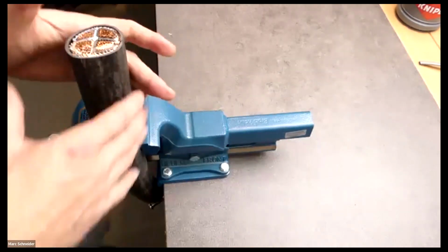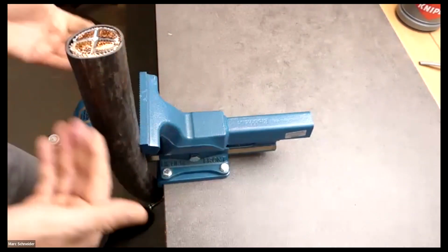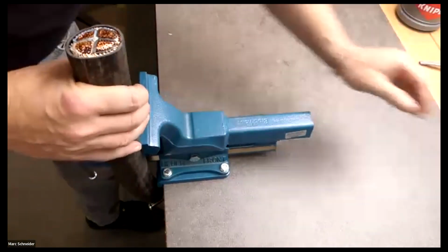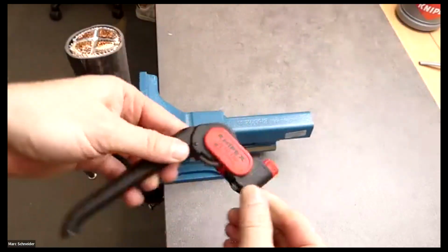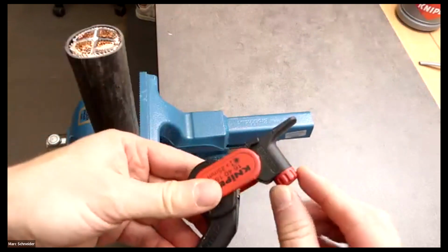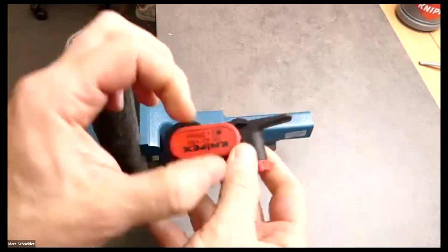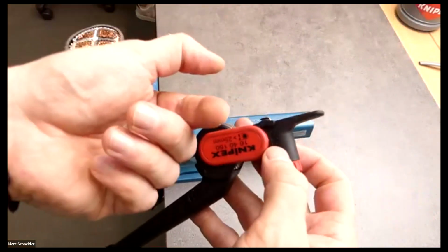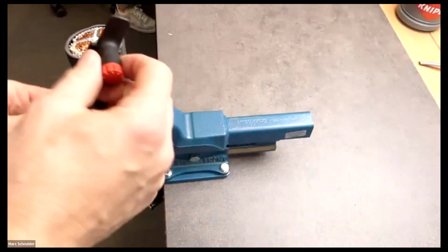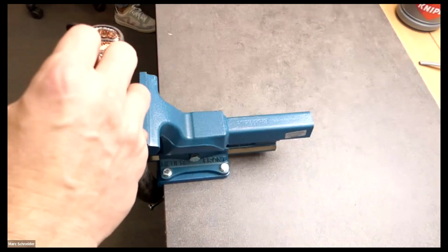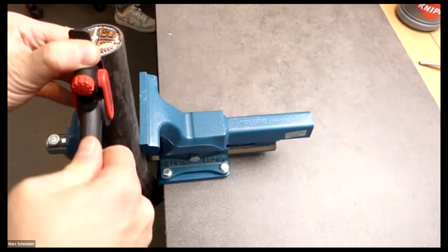This here is a cable. It's an energy cable, an underground cable, which is lying in the ground or in the earth. I think it's a 4 × 70 square millimeter. And this here is the so-called can opener. Here on the red wheel, you can adjust the blade. If you completely turn out the blade, you can change it 180 degrees, and we have additional spare blades directly in the tool. You put it here underneath the outer insulation, give pressure with the thumb here, and then use it like a can opener.